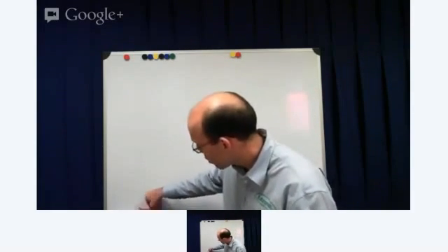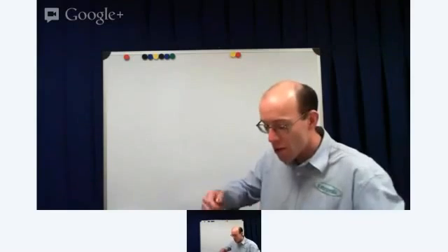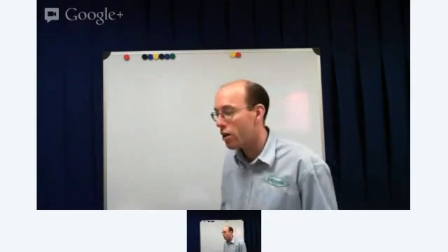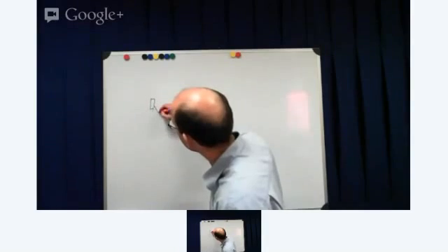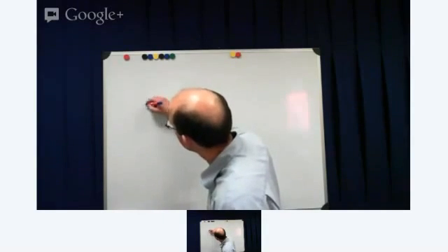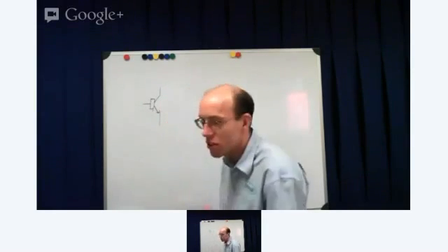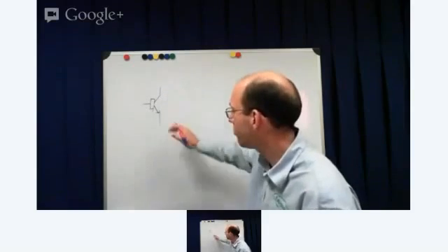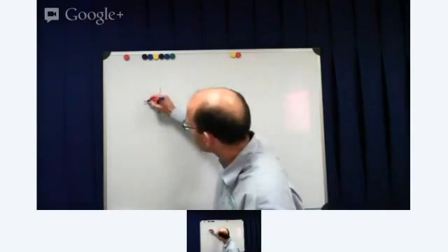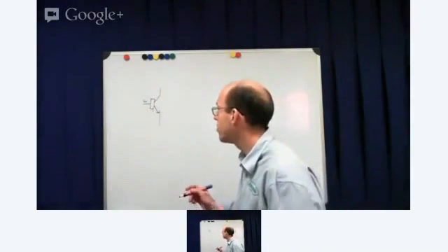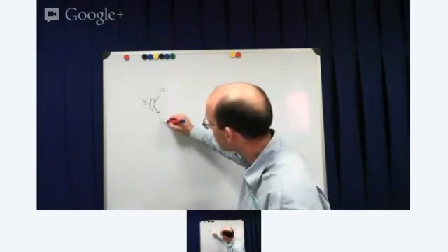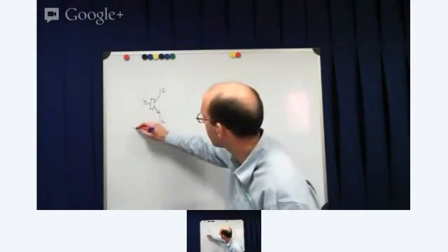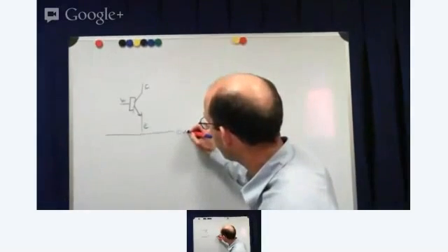Now, there are two varieties of transistors, but I'm only going to really consider one here, which is the NPN transistor. And when we draw it on a circuit diagram, that's what an NPN transistor looks like. It's got three legs on it. The base is the input to the device, the collector is the output, and the emitter in an NPN, we tie that down to 0 volts.